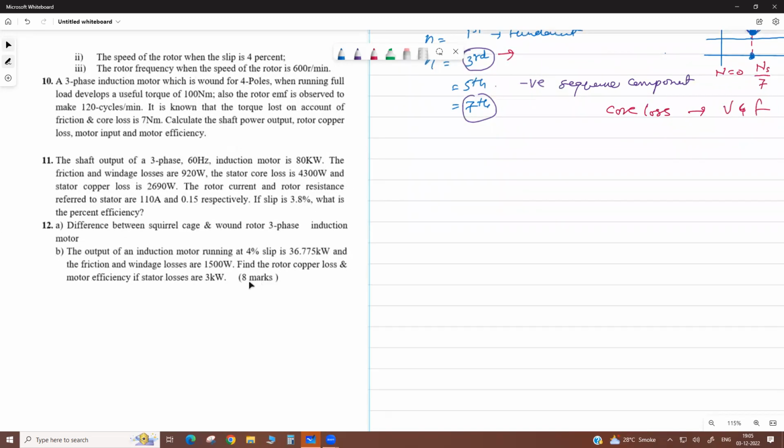Sir, in a dry transformer that we use on board, there is no extra winding to reduce harmonics, right? Because on board we have a delta connection. No, it is not required. As I told, in delta-star also, if your transformer is delta-star, it does not require any additional winding.